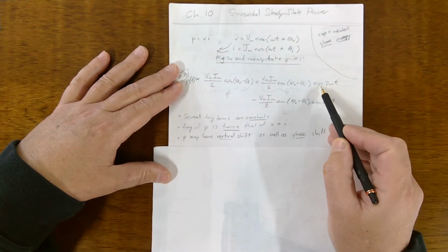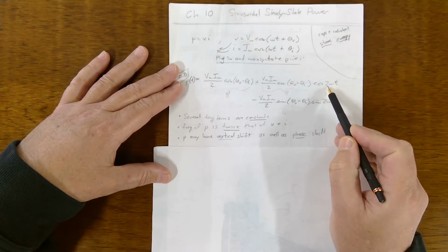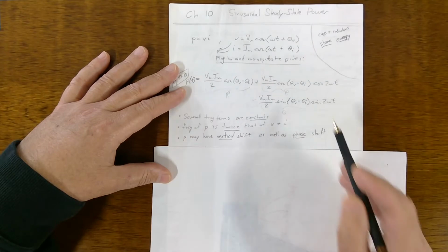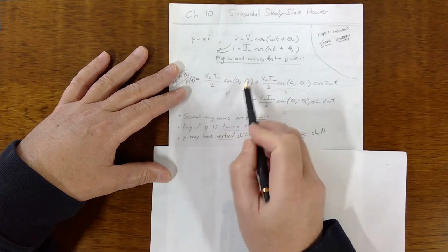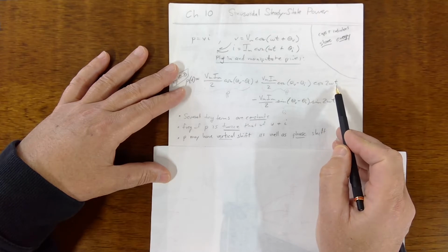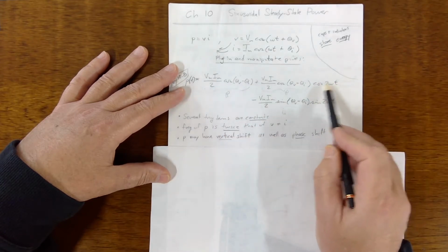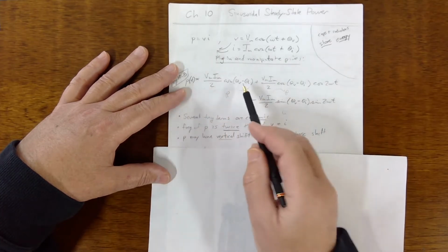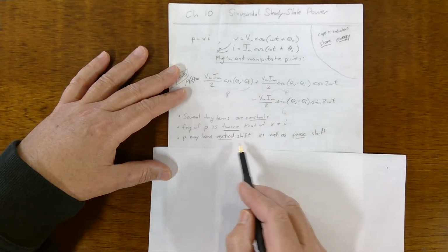Okay, so another thing to note is that in the functions of time, the cosine 2 omega t has twice the frequency. For the voltage and the current signal, it's omega t, but for the power signal, it's 2 omega t. Because of this constant term out front with no cosine function with t in it, it is not a function of time, but this other term is. This constant term just shifts p of t up on the vertical axis. So p can have a vertical shift.